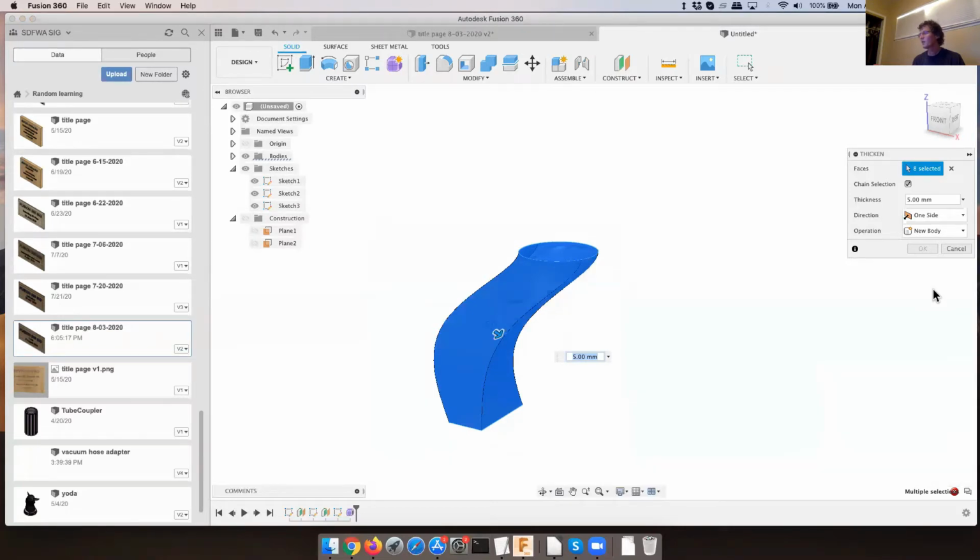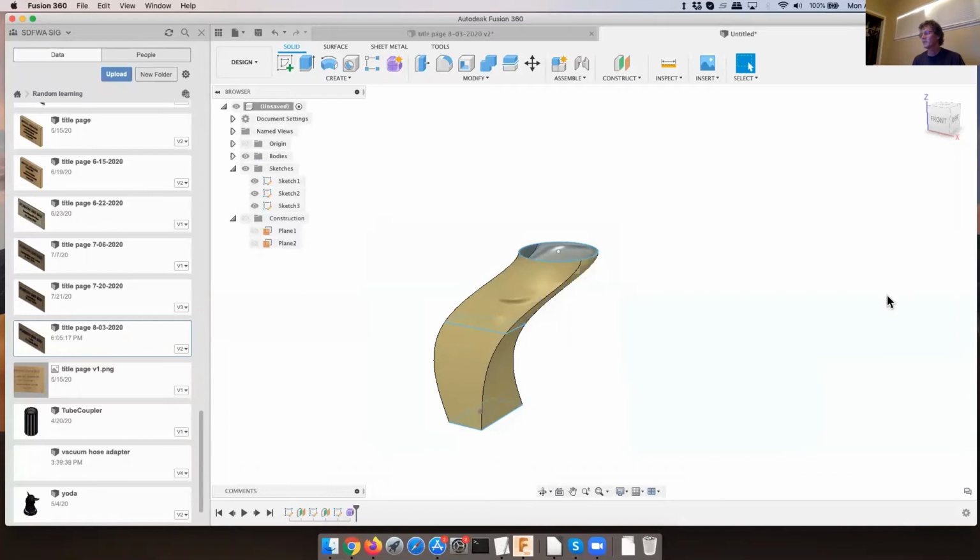And this is one of the complications that comes with forms. So I'm going to scare you a little bit about forms. Sometimes the transitions aren't all captured, and so you need to actually patch them together. I'm not really going to do that right now because it's outside of the Loft feature. But effectively, you need to knit everything together before you can thicken it, because in this case, something we did, there's probably an opening in between one of these seams.